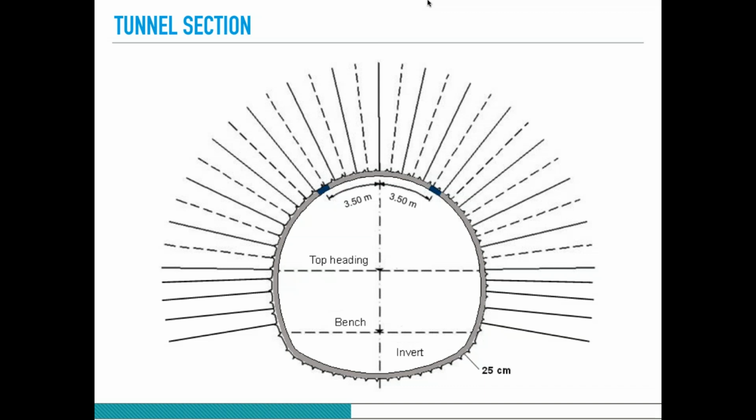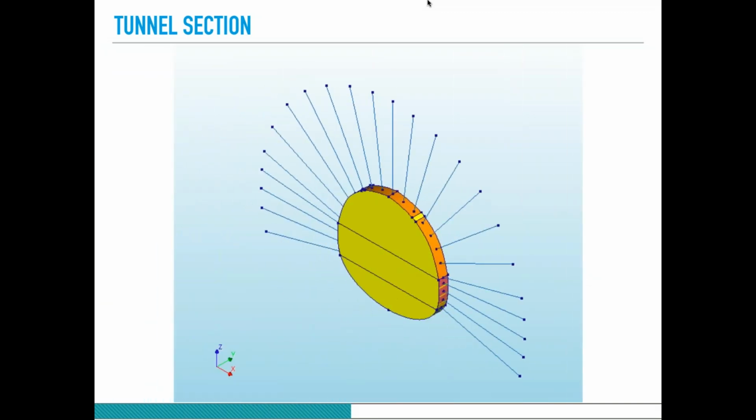Look, here is the tunnel segment, from the tunnel document, and we have one pair of yielding elements in the span of 7 meters. And the excavation is in 3 parts: top, bench and invert of the tunnel, and we have 23 rock bolts around the tunnel section. And this is the way I modeled the tunnel segment. It is a 1 meter section.